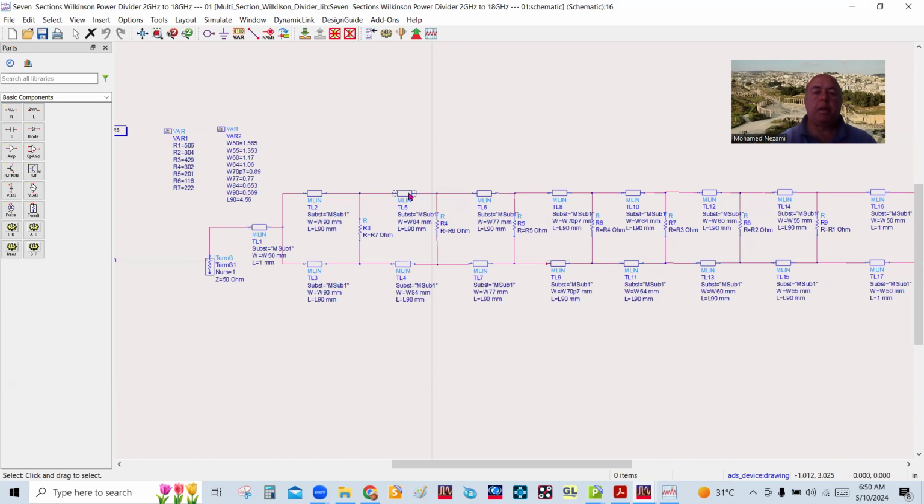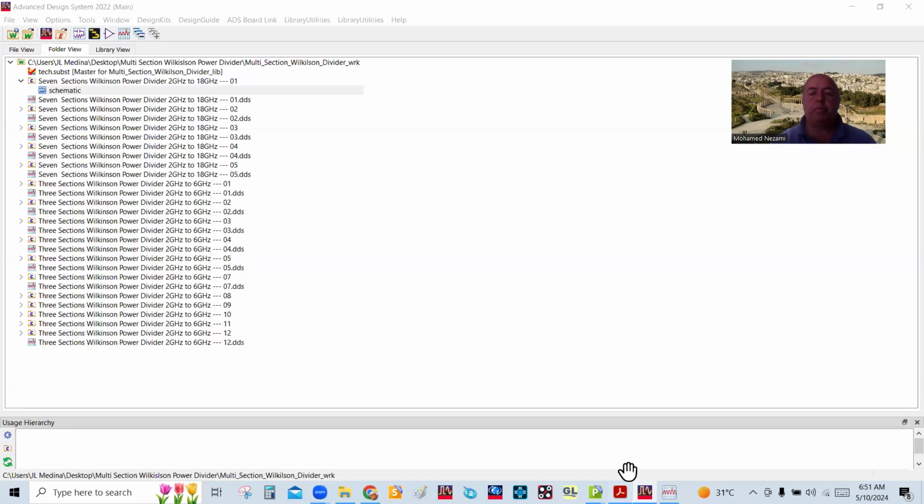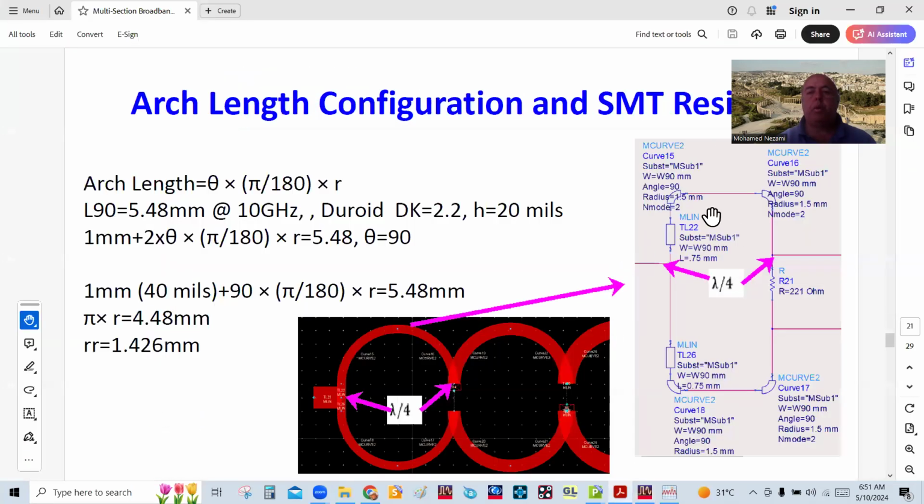Now, these are real transmission lines, microstrip lines, but we don't have any of the curves or transitions to make this circuit. So as soon as we include those, we have to transform first into this topology. We add these 2 line sections to offset space for the resistor.